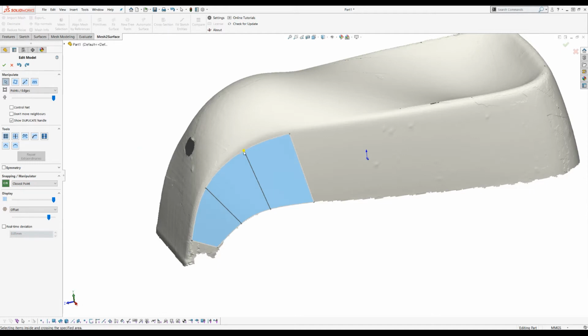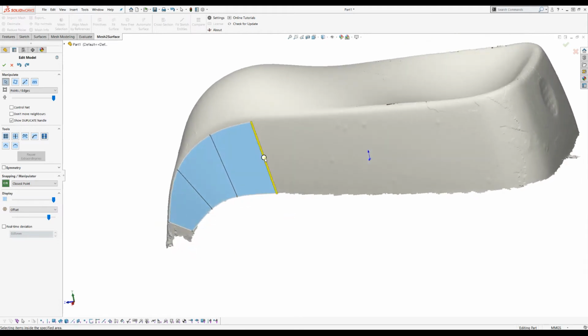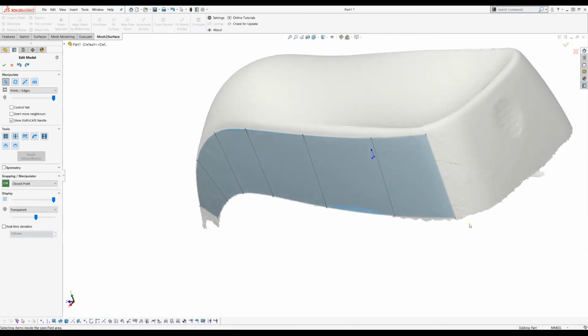As I said, we probably want to just create a stripe here that will follow the surface, and I'll just use my duplicate button here. When I drop my mouse, you see that it's snapped to the mesh, and you can tweak and adjust your shape. We'll just move here. As you see, because the mesh is not transparent, when I move, it's behind the mesh, so you can just play with the transparency to see your results. And this is how I create my strip. You see how easy it is.